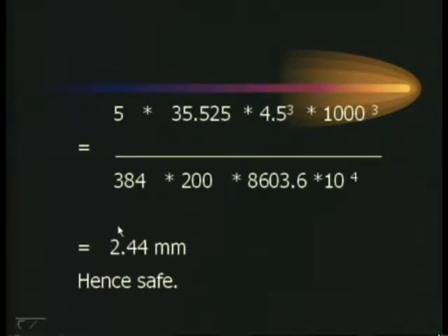So, with this, I am confident that you are able to design a very simple beam. Simple beam in the sense, you can choose a section from your steel tables, either I section or channel, whatever section is appropriate you feel.